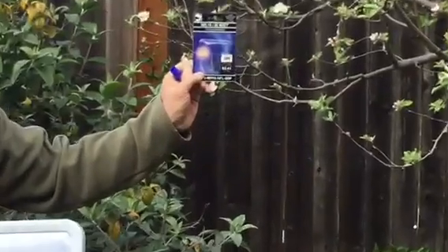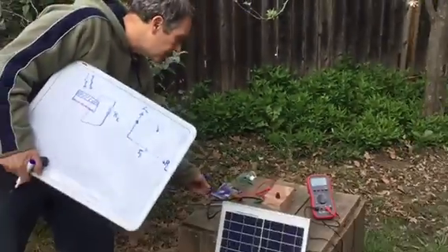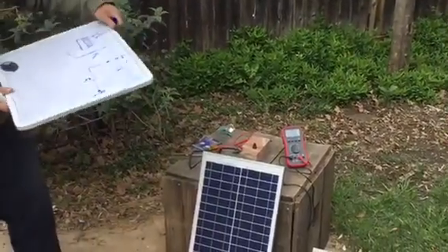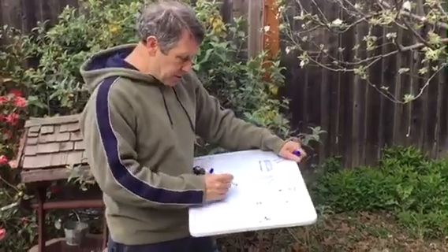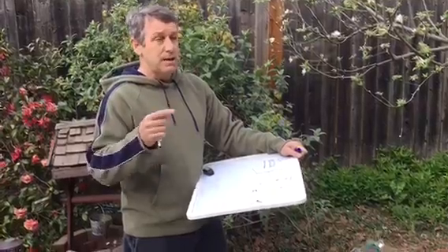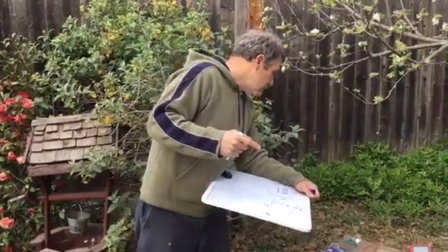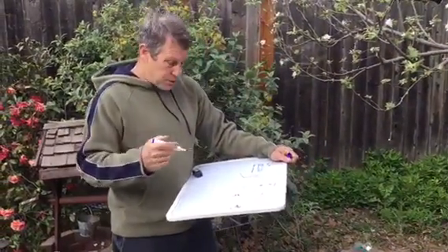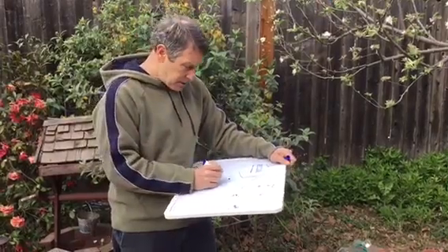Assuming these numbers are approximately right, it's a 12-volt bulb, and it's supposed to produce 20 watts. So if we hook that up to 12 volts, we'll get 20 watts. A light bulb's basically a resistor. So if you could, maybe you could write that down and pause the video and see if you can work out the resistance. I'll be doing it myself. Just make power equal to 20 watts and voltage equal to 12 volts. What's the resistance?